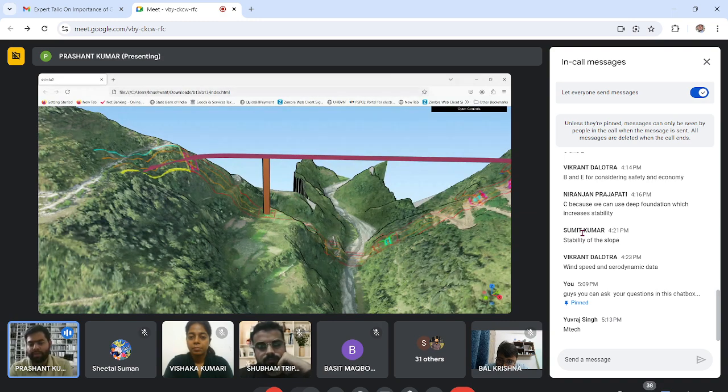So suppose someone has taken a very basic PMGSY road project. Just download the DEM file of that location from the United States Geological Survey, set the coordinate system in QGIS, and import that data there. As I said, add a vector layer and draw your road by hand on GIS. After that, you can go to Civil 3D, refine that alignment, design it, then make it into a 3D model. That's how you can do it.